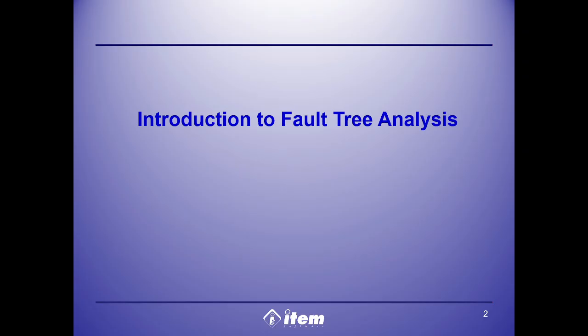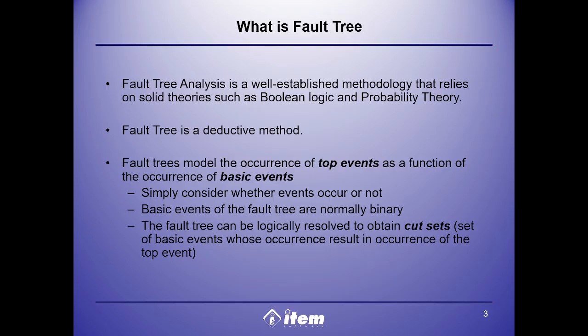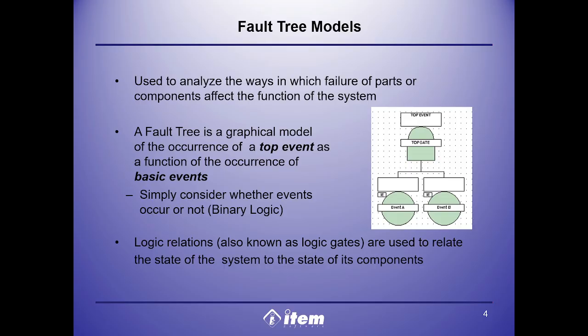We will begin by introducing the most widely used tool for this top-down approach, fault tree analysis. So what exactly is a fault tree? At its core, fault tree analysis is a graphical, deductive technique that focuses on a single, specific undesired event, which we call the top event. This might be a catastrophic failure, like the vessel explosion we discussed in our case study, or any critical system-level hazard. The analysis works backward from that top event to identify the various pathways of equipment failures, human errors, or environmental factors that could lead to it.